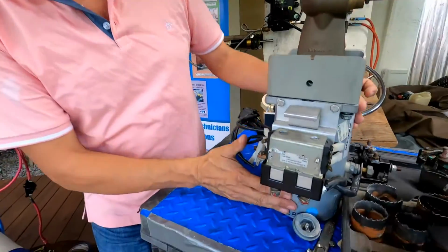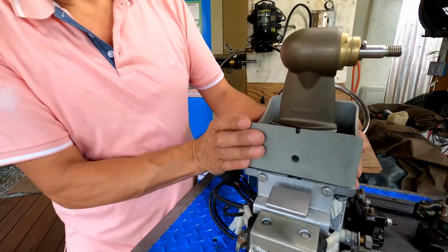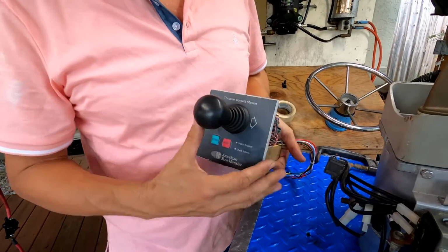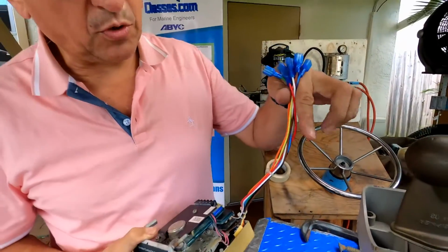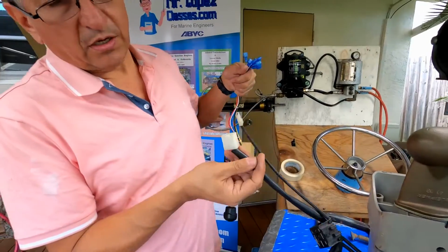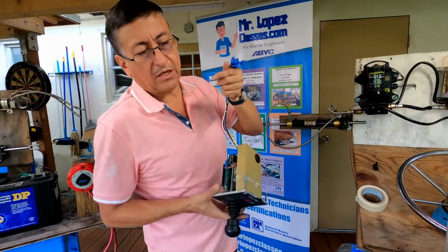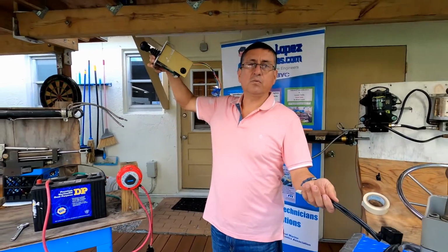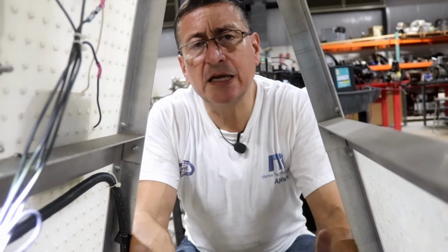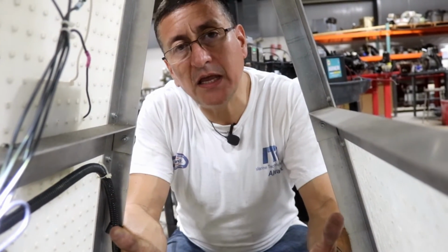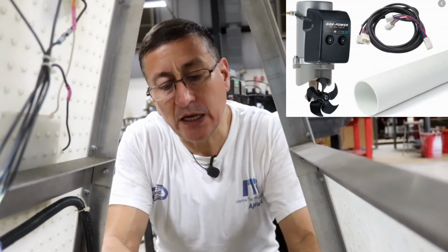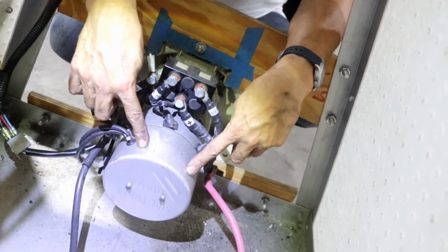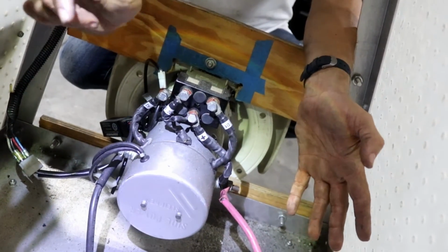This is the reversible motor, the solenoid control box, the bracket for the tunnel, and the lower unit. And of course we have the control, the joystick, and the joystick cables are connected with the harness to the motor. The joystick is on the console, and it is connected with the motor. This is a bow thruster or a stern thruster, exactly the same as the bow thruster that you have on the screen. It's a typical DC reversible motor, 12 volts or 24 volts. This one in particular is for 24 volts.